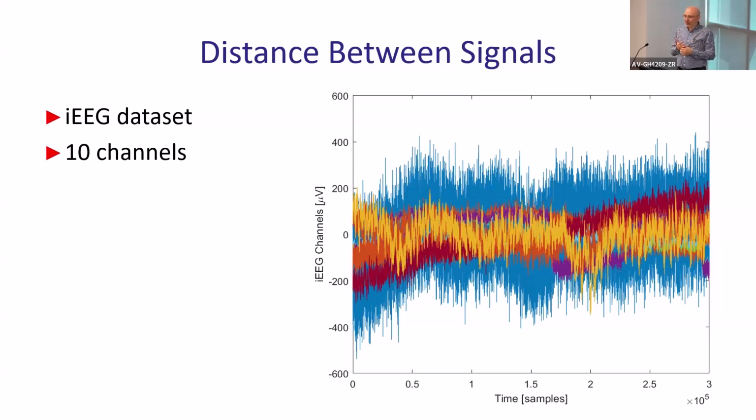You have all kinds of ways to define zero, which is ground. In electrical engineering, we typically do not have that problem because you're just using actual ground. On the body, you cannot use that. So it's all floating. And you also have DC drift, which is a typical phenomenon where signals just go on DC bias, which is an artifact of the recording device because you don't have any ground to measure zero. Zero is floating and could be anything. And could also be noisy. So you get horrible SNR, signal to noise ratio, and you get signals which all look like pretty much pure noise. And you need to extract some information out of it, like how similar they are, how close they are to each other, how to filter them, and all these questions.